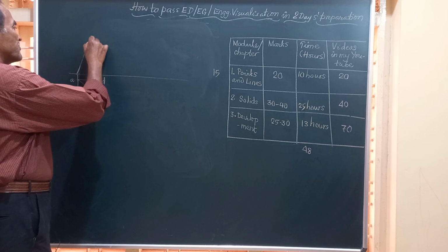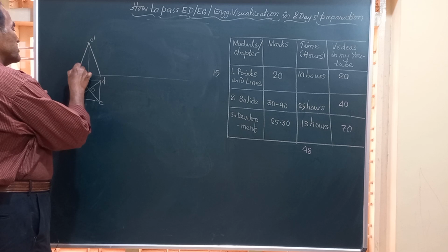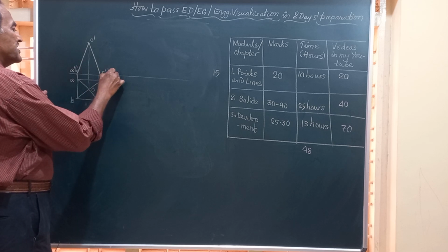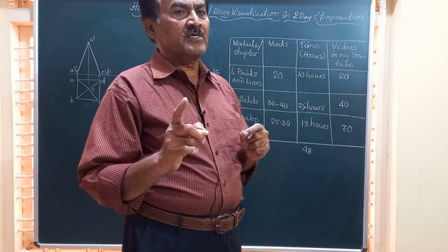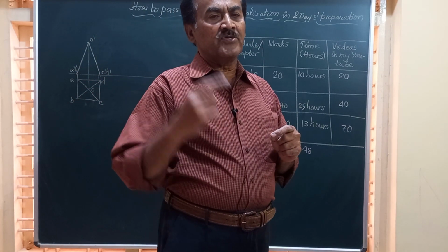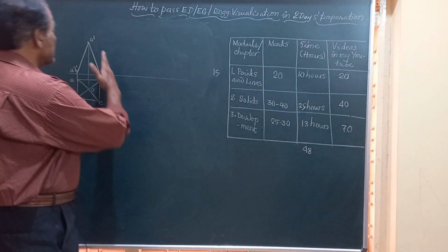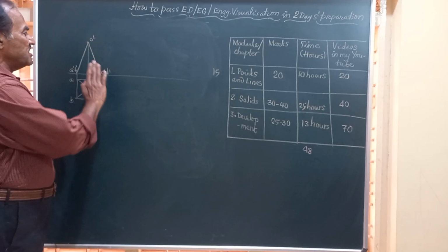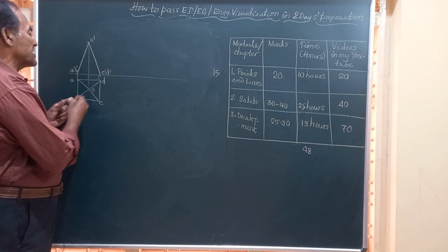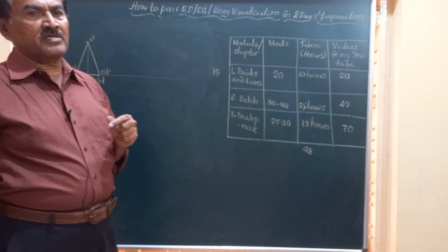You can write down the front view and top view correctly. This is O dash, A dash, B dash, C dash, D dash. So after writing the initial position, if you are intelligent, you should check what the line on the extreme right hand gives you, because generally the object is tilted to the right side of the observer after the first position.